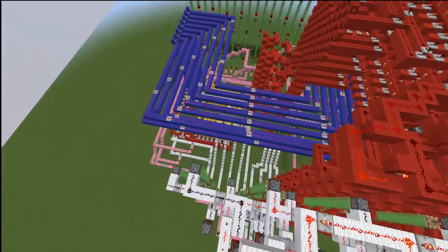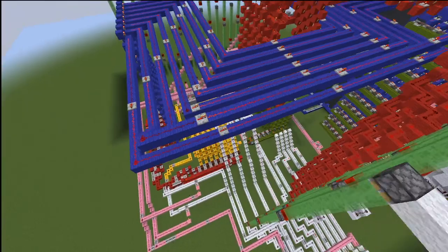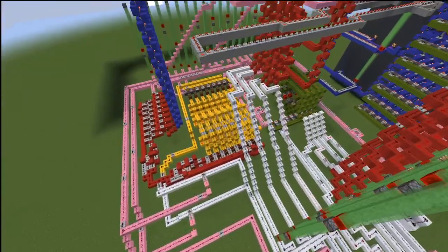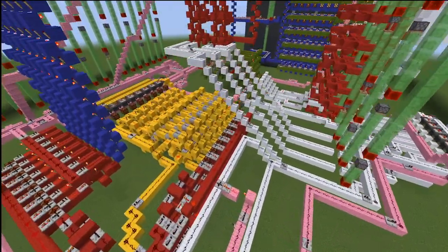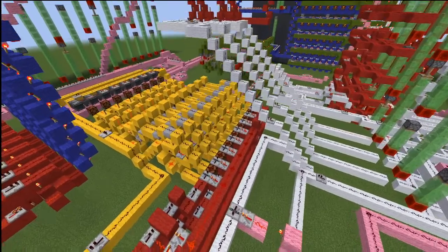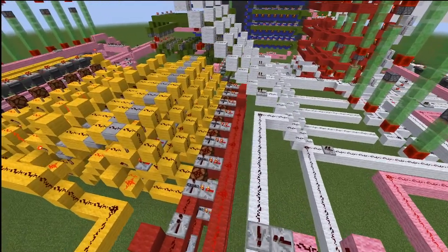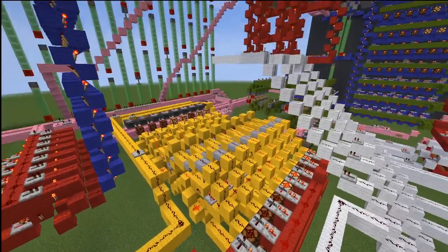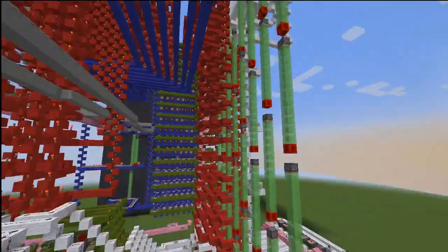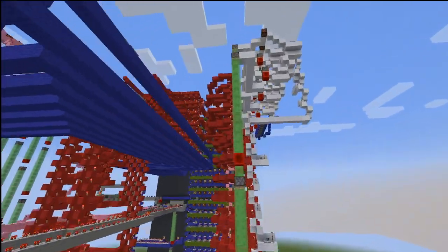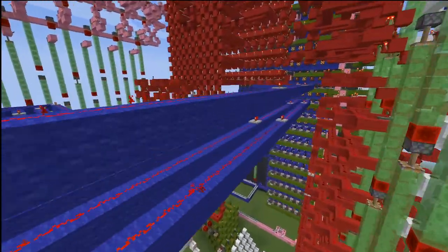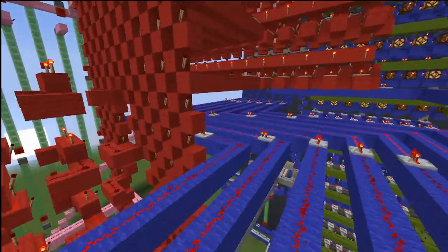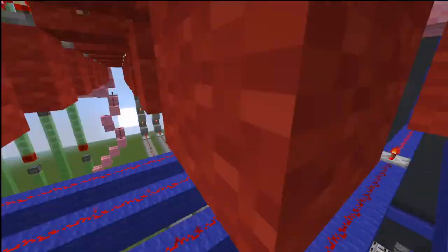And now if we drop down below on the next clock cycle, it's going to write that data from the address and data bus to the A register here. And there it is. You can see it copied it over. And so now we can go back to the clock cycle, and that's it for load the accumulator.